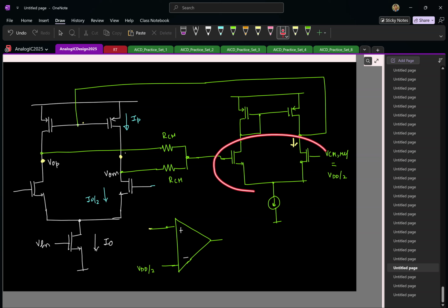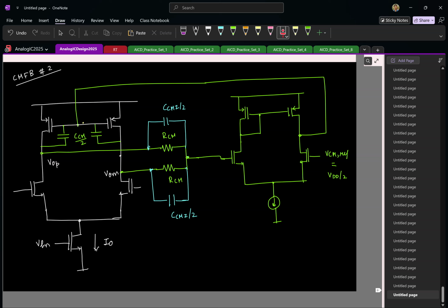Yeah, here I used an NMOS variant. I could also have used a PMOS variant. So the question is, do you think using a PMOS variant is better, or this is better? How will you determine? Sorry? Why? Yeah, gate voltage is VDD by 2, but VDD by 2 is half the supply, right? Both NMOS and PMOS will be equally fine. But you're going in the right direction. Because for small signals, is there a difference between an NMOS variant or a PMOS variant? If at all there is a difference, where should that be? Large signal or DC biasing, for example.